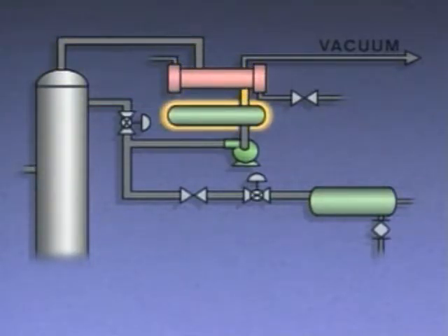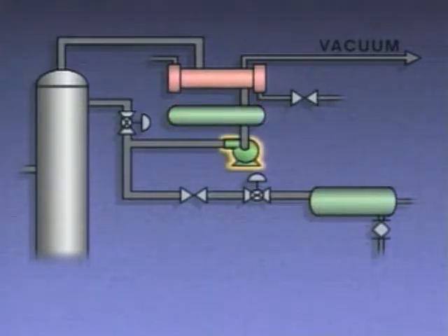When the condensed vapor reaches a predetermined level in the receiver, the reflux pump is started, and a temperature controller is used to open a valve in the reflux line. All of the condensed overhead vapor then flows to the column as reflux. At this point in the startup, vapor is rising up the column and liquid is flowing down the column.